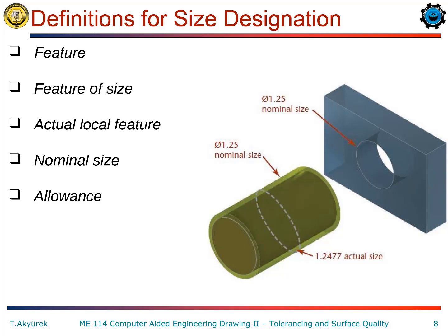In order to ensure the assembly, function and interchangeability of a part we design or manufacture, it must first be within the boundary of a dimensional accuracy and then the geometric accuracy. We call this limit definition a tolerance. There are maximum and minimum points for this limit. In order to ensure the compatibility of the parts, it must first be dimensionally compatible.